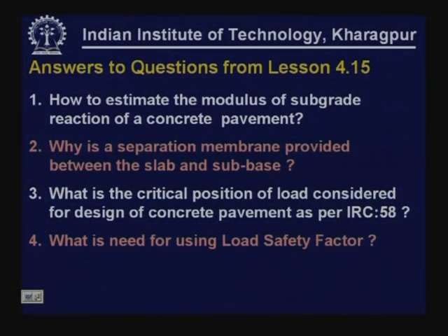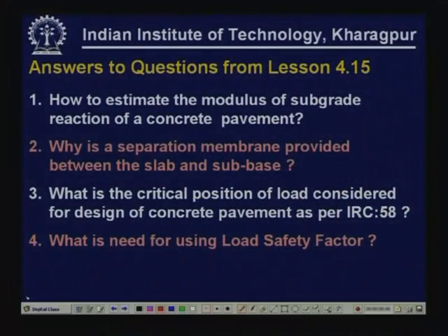What is the critical position of load considered for design of concrete pavement as per IRC 58? Concrete pavement considers the edge position. The wheel load has to be placed in the edge region. This is considered to be the critical position for wheel loads.